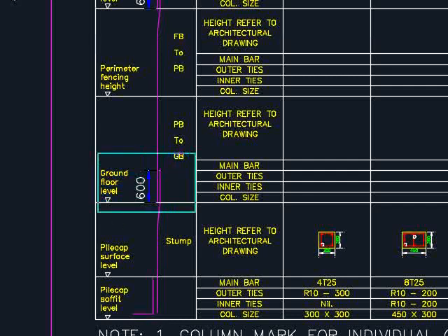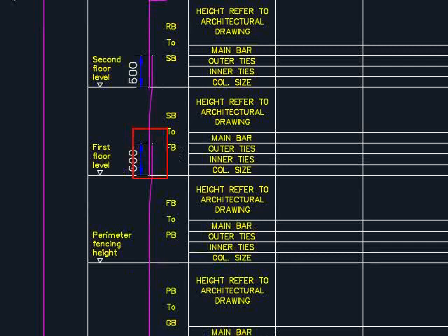And then the reinforcement bar from the ground floor level will go up straight into the first floor level, and there will be bar extruded from the first floor level to be lapped with the subsequent column in the first floor level by at least 600 mm. This process should proceed to the second floor level until it ends at the roof level. This is about the lapping of the reinforcement bar in the columns.